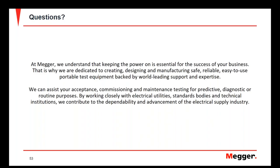So Jason focused on primary injection testing, and he also mentioned secondary injection testing. Besides that, some of the other tests that can be done include insulation resistance, where you check the insulation of the breaker. You can check the insulation between the poles, and between the poles and ground on the breaker. And the other test that you can do is a contact resistance measurement.